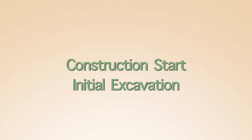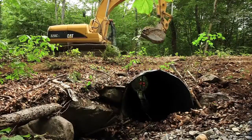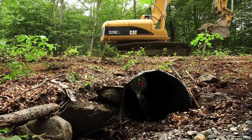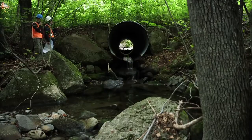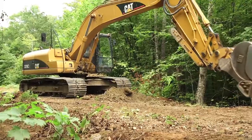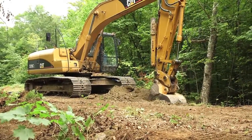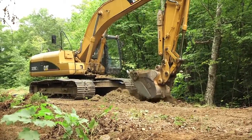Construction start, initial excavation. If carefully done, a large portion of the excavation can be done before the water control is initiated, as long as sediments can be kept out of the stream. Here is the pipe prior to the start of excavation. A portion of the road fill over the existing pipe was removed prior to dewatering being initiated. Dewatering was not needed up to this point, as all excavation was kept away from the stream.